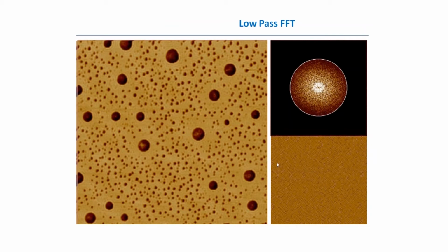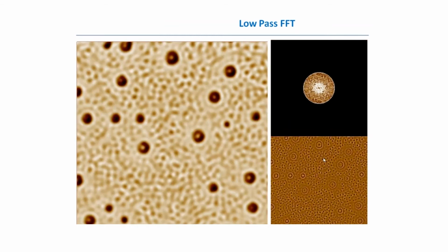From the right bottom, you can see the difference, and you'll see that really high frequency noises have gone. But again, if we use this filter too much, meaning that we decrease the band of the filter too much, we'll start to see that the image has lost plenty of details, and in the difference between the result and the original image, we see that the objects really start to appear.